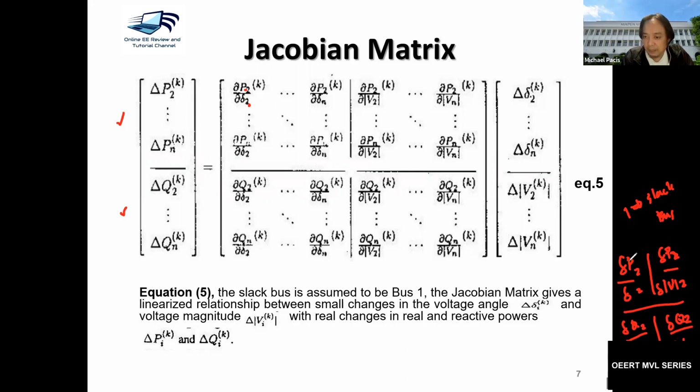Okay, real and reactive powers. And please take note of what we have developed here. This is the change of the angles and the change of the voltage magnitude. Because at the end of the day, we can solve those voltages and those angles. As you can still recall, in the Gauss-Seidel method of successive substitution, we have voltage 1, which is definitely your slack bus. We start at voltage 2, and whatever the voltage at 2 will be reflected at 3, and then you repeat again at voltage 2 if the tolerance error is not achieved. So you substitute until you reach the tolerance error.